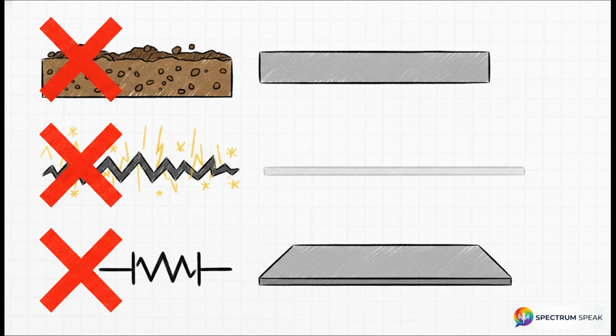Let's rapid-fire debunk these three massive myths, straight from Henry Ott. Number 1. The Earth is a low impedance path. False. The impedance of dirt is orders of magnitude greater than a simple copper wire. Number 2. The Earth is an equipotential. False again. Because it has such high impedance, any current flowing through it creates massive voltage differences across the surface. And number 3. Conductor impedance is determined by its resistance. False. Remember the mathematical derivation we just did? We proved mathematically that impedance is heavily dictated by inductive and capacitive reactance. Copper conductors that are dynamically shape-optimized to lower inductance will always beat the dirt.